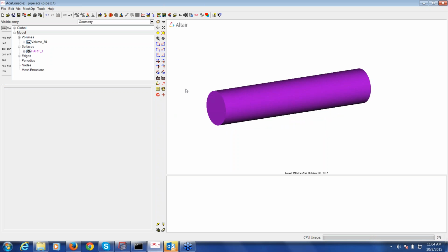So the objective of the simulation is to do a CFD analysis of a pipe. So water is flowing in the pipe with inlet, say a certain mass flux or something. So basically how the flow is actually flowing. Okay, and basically to see the velocity and the pressure drop of the system. Okay, so right now for doing the CFD analysis, we need to make sure that we have an inlet and outlet of the pipe and the wall basically, which governs the surface, basically bounding of the pipe.